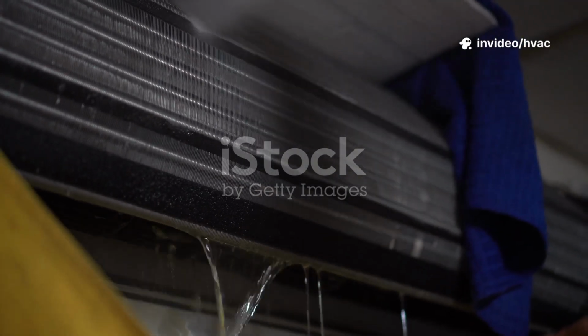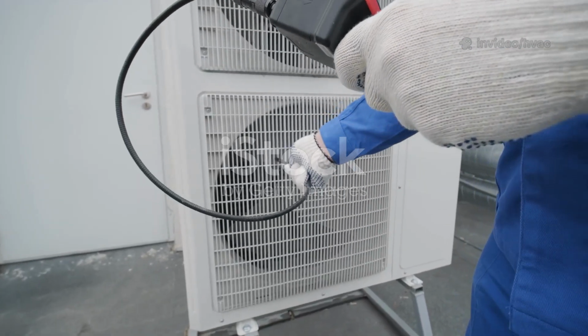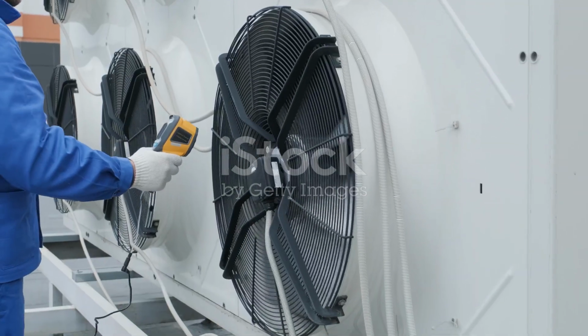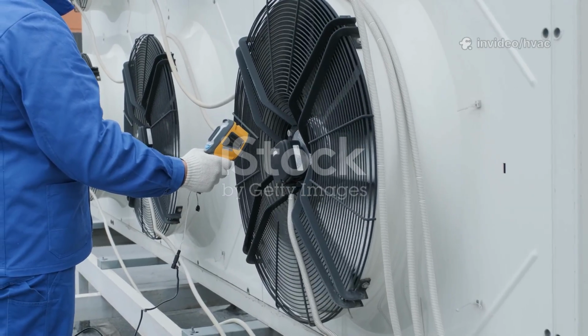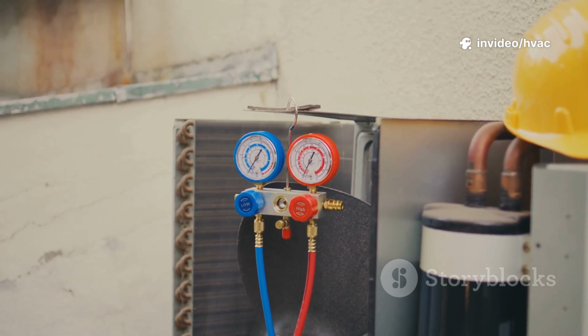Coils are where the real temperature change happens. Measuring air temperature as it leaves the coil is critical, especially for cooling coils to prevent freezing. Single-point sensors don't work here. You need an averaging sensor to capture temperature variations across the coil face. Freeze stats are often averaging sensors for this reason.